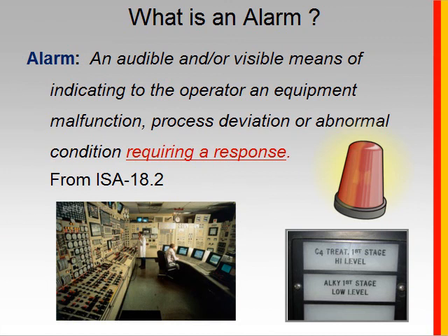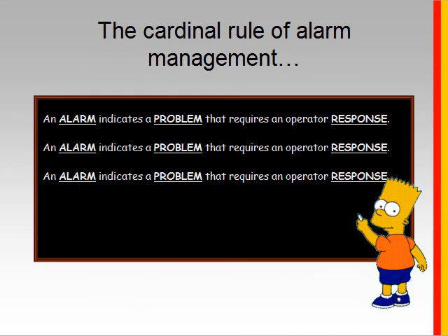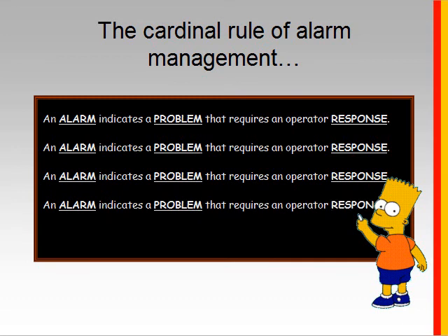One of the key parts of the philosophy is definitions, and here's the definition of an alarm according to the ISA 18.2 standard. An alarm is an audible and or visible means of indicating to the operator an equipment malfunction, process deviation, or abnormal condition requiring a response. Emphasis on the words requiring a response. Seems like a pretty simple concept, but from it we derive the cardinal rule of alarm management, which says that an alarm is used to indicate a problem that requires an operator response.